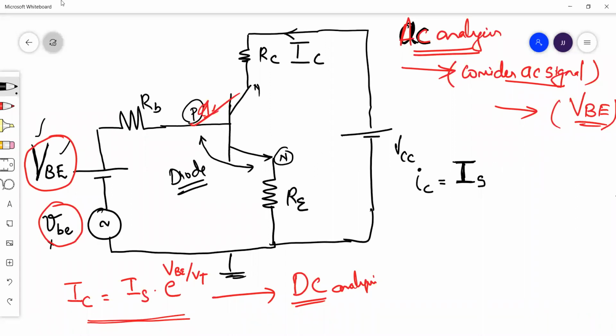It is a constant value, or rather a temperature dependent factor. It does not depend on the voltage we apply. Only it is depending upon temperature, the reverse saturation current. So that must be capital IS into e raised to the voltage applied divided by eta VT, minus 1. This is our equation.